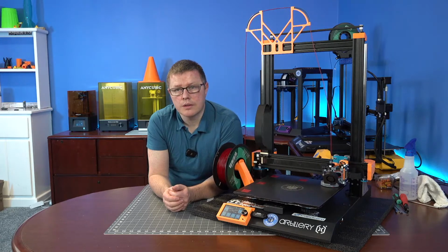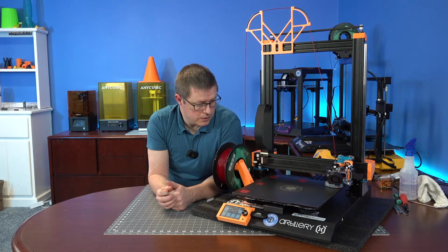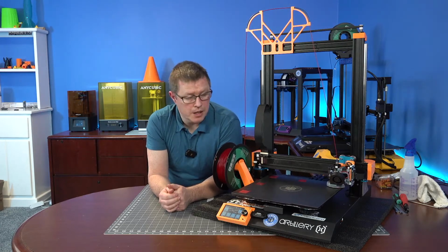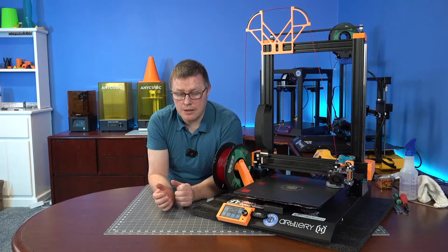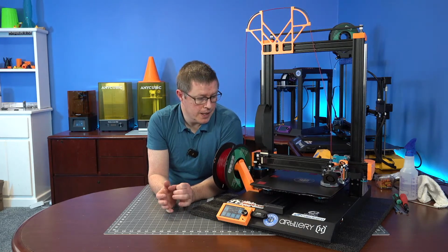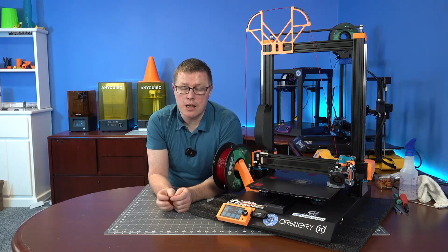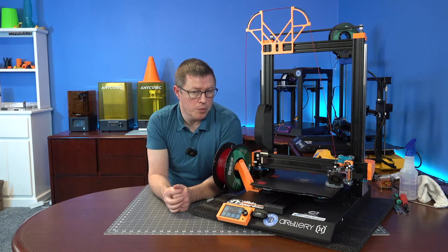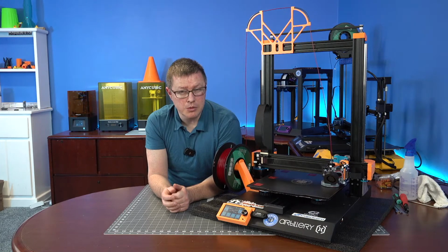Drew asks, if one was to print your Sidewinder X2 Hemera mount and fan, what print settings / filament would you recommend? So I would recommend PLA because you're not worried about any sort of heat or strength issues other than maybe a little rigidity. And PLA, while not being quote unquote as strong as PETG, it is more rigid. So if you want rigid prints, use PLA, where PETG is a little bit more flexible.